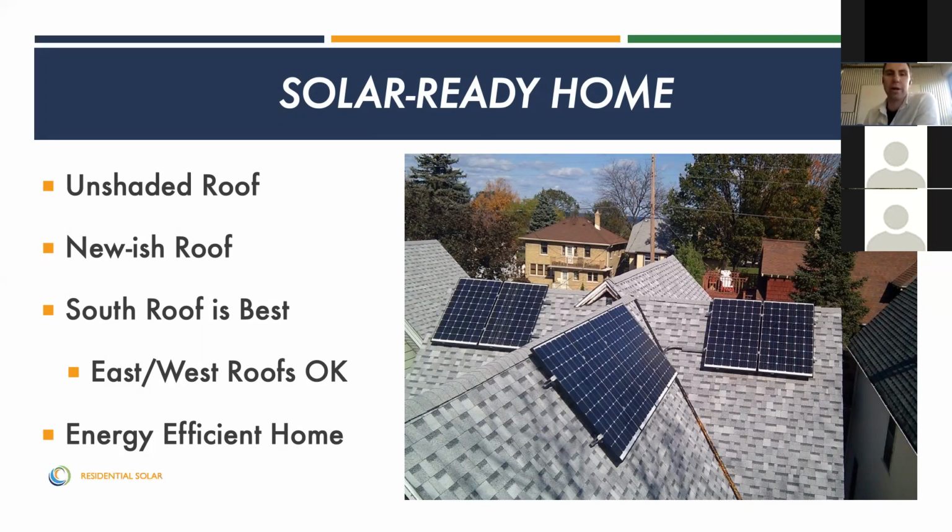If you can go in with a brand new roof, that's great. If your roof is over 15 years old, you're probably going to want to think about replacing it. But if it's less than 10 years old, you're probably safe. So again, we want that because if you have to, at some point, have your panels removed and have your roof reshingled or redone, that's definitely going to eat into your return on investment time. So we definitely want to go in with a structurally sound roof right at the beginning.